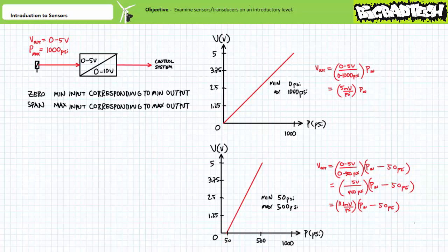Regardless of the method employed, the same pressure sensor is being utilized, and realize it is still hard limited to 1000 psi. If either system ever experienced a pressure spike above 1000 psi, the pressure sensor could be irrevocably damaged, an example being the permanent distortion of the diaphragm to maximum deflection. In this case, the unconditioned sensor output would continuously flatline at 5 volts and cease to report any usable data.